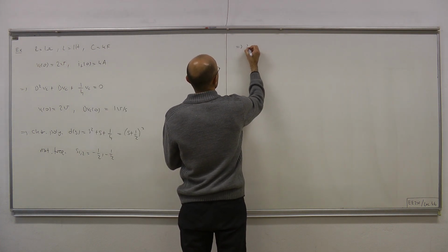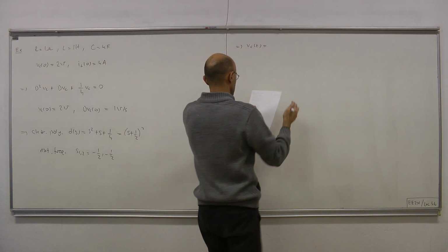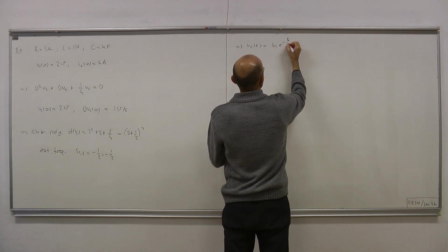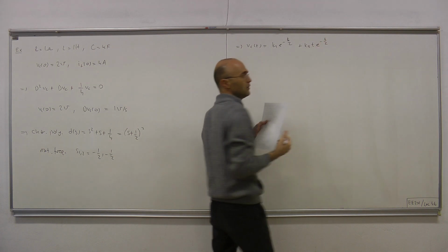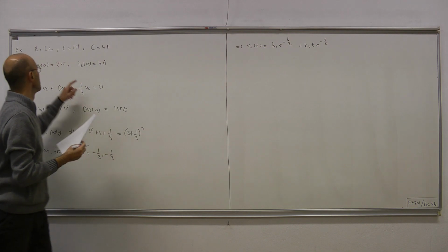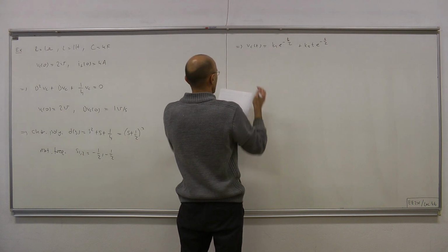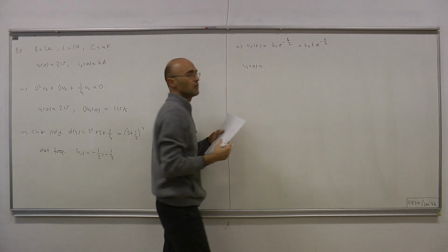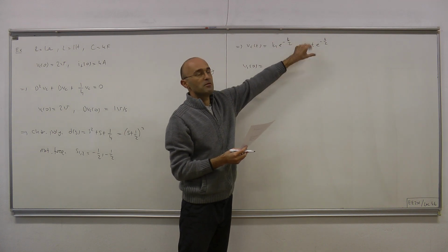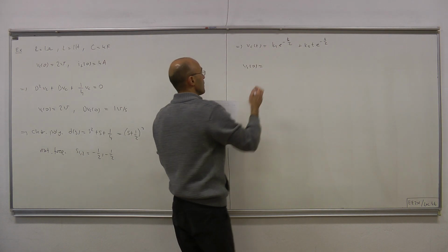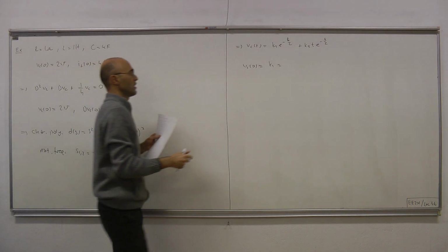Okay, so Vc(t) is of the form k1 e to the minus t over 2 plus k2 t e to the minus t over 2, because we're dealing with the critically damped case. Okay, so when you plug in t equals 0, due to that t term, the second term disappears, and what we have is k1. And Vc(0) is given to be 2 volts, therefore k1 is 2.